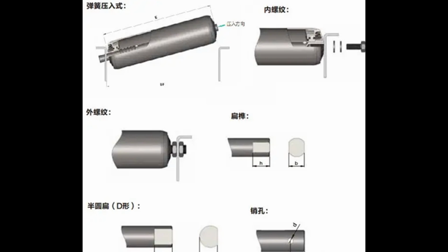2. Internal thread. A. It is the most commonly used installation method for power conveying such as sprocket rollers, and the rollers and frames are connected through holes with bolts at both ends. B. It takes a long time to install and dismantle the rollers. C. The rack installation hole should not be too large, in order to reduce the height difference of the roller after installation.